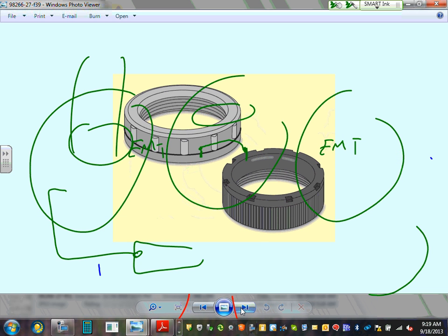Different types of insulation bushings. We use an insulation bushing if the conductors are number 4 or larger, guys. If you push a big fat conductor through an EMT conduit, how many of you have pushed a few of them, right? If you push a conductor through an EMT conduit or a rigid conduit, as you push, you will damage the insulation, especially if the conductors are big.